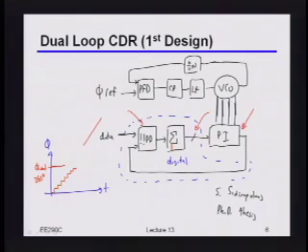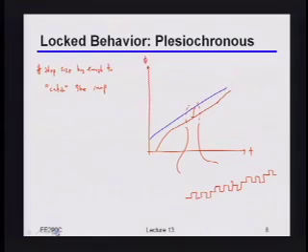And especially if we're just looking for things that have pretty low bandwidth, it's a waste to be doing 12 gigahertz logic on something that's only drifting at degrees per millisecond. So typically you won't work on this full rate data, but you'll decimate it, send it to some lower rate and work on things at that lower rate. Again, we'll talk about that in more detail in 1 second.